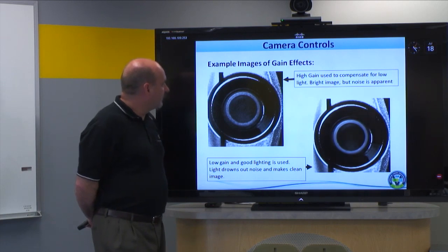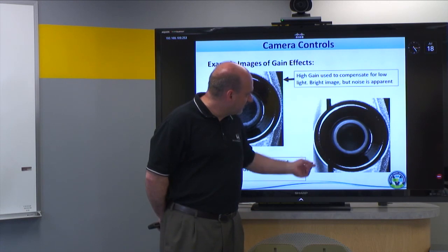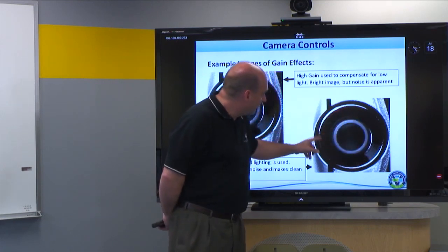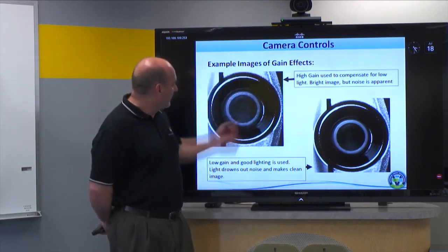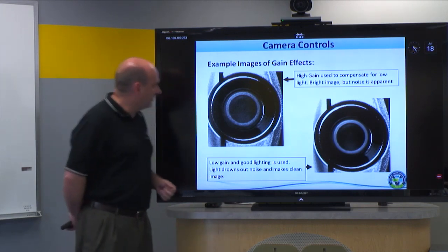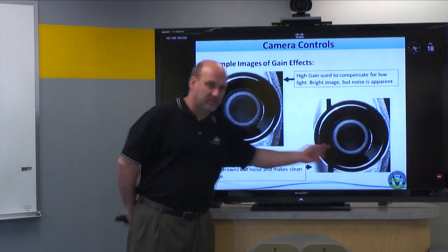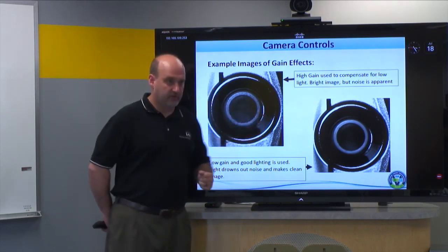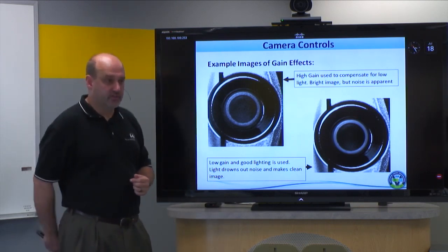So if we look at this, what's the practical effect of this? Again, this is an amplified image for sample here, but if this image was taken with the same camera at low light, so if I look inside this lens here, I can see the center of the lens, I can see all the grayscale variations in the ring out here, and in fact the shiny ring. This was taken by using a longer shutter and lower gain, but now if I turn the gain up and make compensations to the shutter, then this is the same image. Notice the exposure is the same. I can still see the ring. The grayscale values are approximately the same, but you can see how much more noise is in this image, and that comes directly from the gain amplifying the noise in the camera and using a smaller percentage of the well capacity that's available in this particular camera.